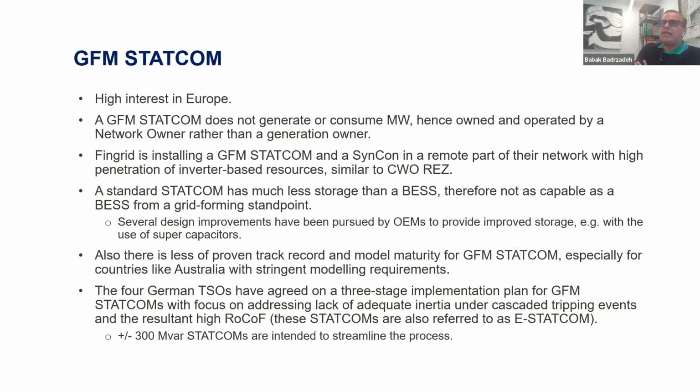And then the second aspect, like I mentioned, is the relatively smaller energy storage, and not just in terms of magnitude, but in terms of duration as well, because you basically have capacitances, and the energy storage for capacitance is very short term. So this is the second disadvantage of HVDC, but obviously this is based on today's technology. Things are changing very rapidly.